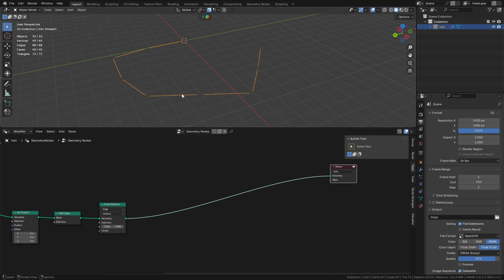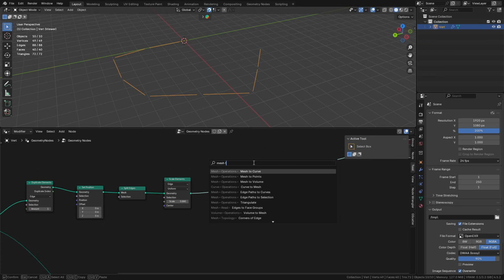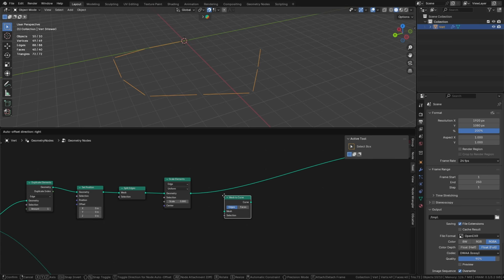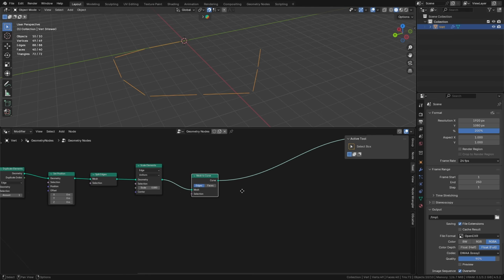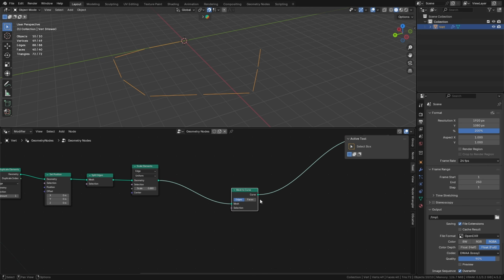These edges, we're going to use them multiple times, once for the bottom of the mesh, once for the top, and once for creating the left and right edges. So first let's create the bottom edge. We have to convert it to a curve again, so that we can use a profile, particularly a circle, to create the cylindrical shape. It's going to be clear in a minute.